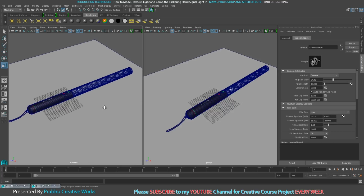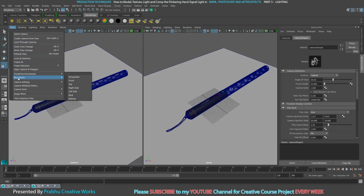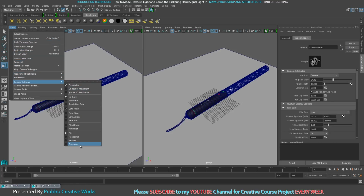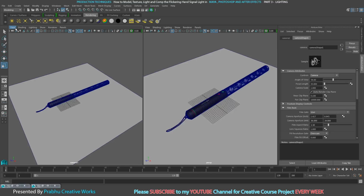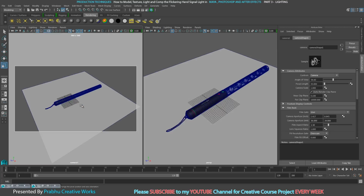Then you want to set two things. Go to view, camera settings, and choose overscan, and then go to view, camera settings, and choose resolution gate. It has 960 × 540. It's too high for our basic render. So when you start lighting, you want to keep your height and width relatively low.